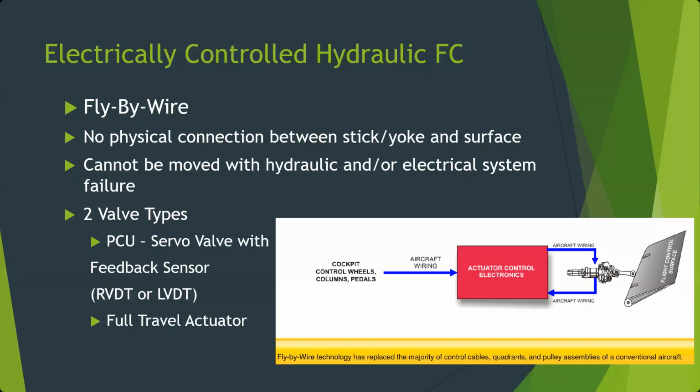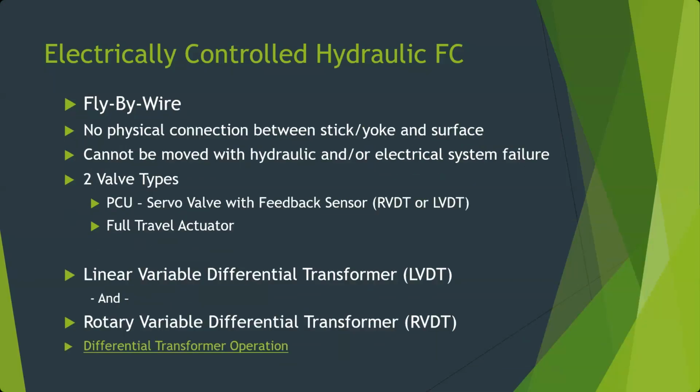You can also have your full travel actuators, the things that are either fully extended or fully retracted. Flaps, kind of, and they have stops, I guess, so not a great example, but things like ground spoilers. Slats will even have steps. They'll go through different steps. They're not always fully extended.